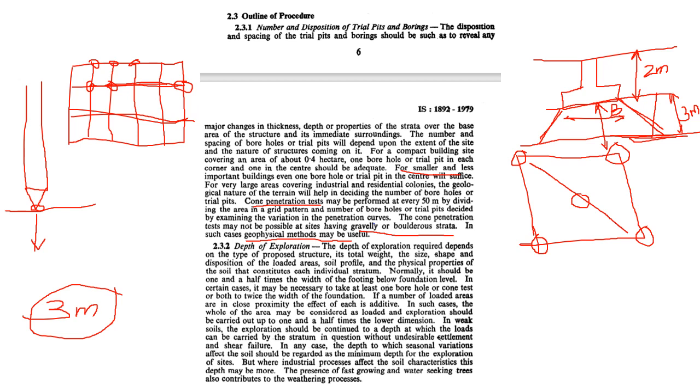Okay, so it is important that you assess the bearing capacity at that point as well. So the code will give you the recommendation of this significant depth up to which your loads are getting transferred below each type of foundation.